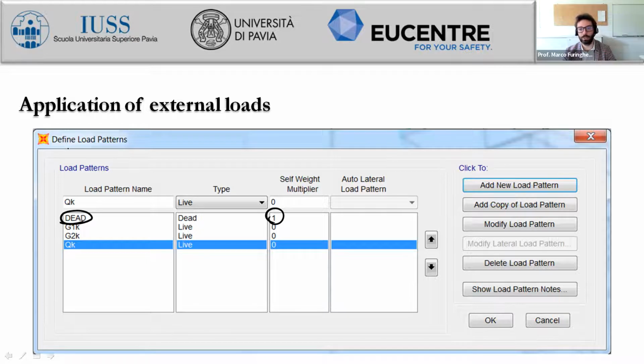So this leads to shear and bending moment. But if we consider columns, this distributed load is perfectly aligned with respect to the axis of the element. So this means that we will have a distributed load with respect to the axial behavior of the frame element. So that will imply just the variation of the axial load without any shear and without any bending moment.